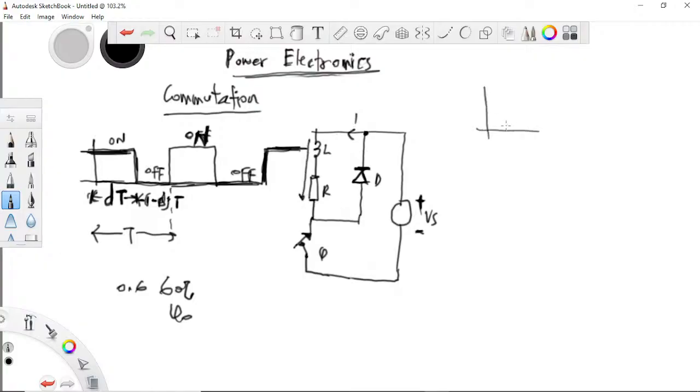In the inductor, please pay attention, here I'm in the on state, the switch is on. There's current in this load, so it will rise. When we say inductor, the current just doesn't jump. The current rises, it transients through the inductor. So therefore, the current rises.